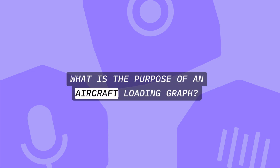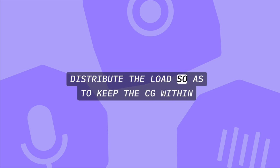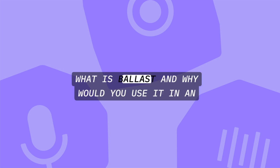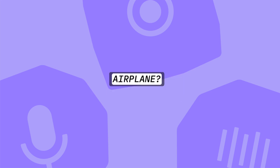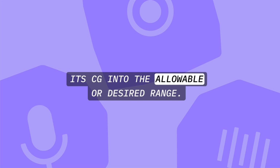What is the purpose of an aircraft loading graph? It is a method for determining how to distribute the load so as to keep the CG within allowable limits. What is ballast, and why would you use it in an airplane? Ballast is weight added to the airplane to bring its CG into the allowable or desired range.